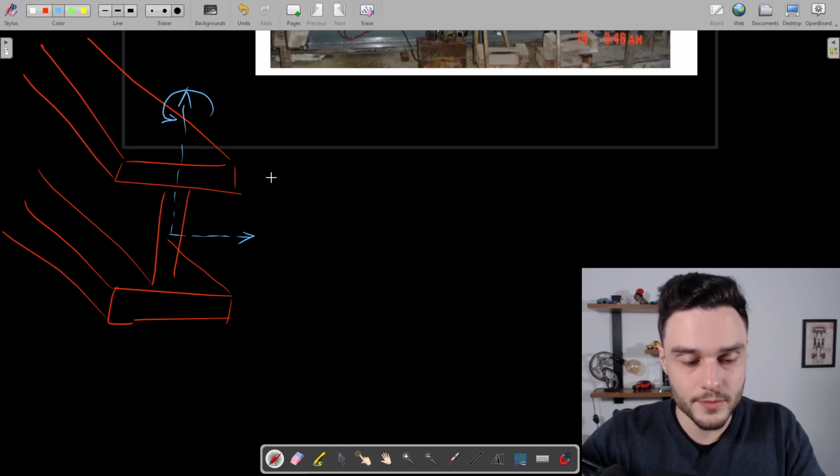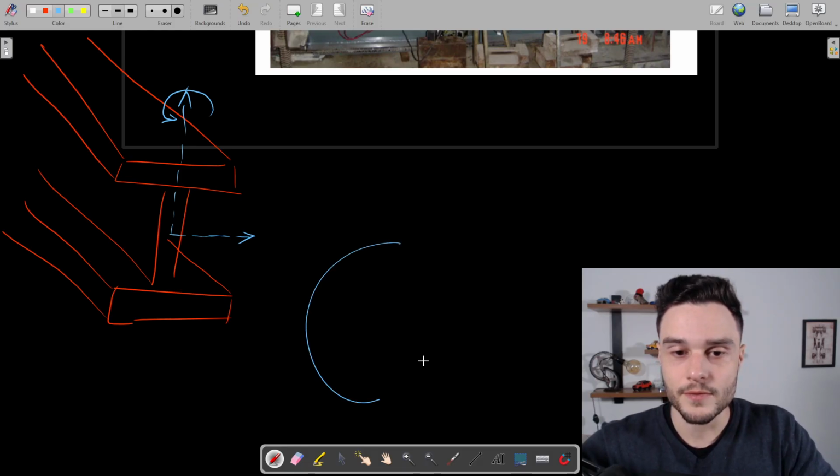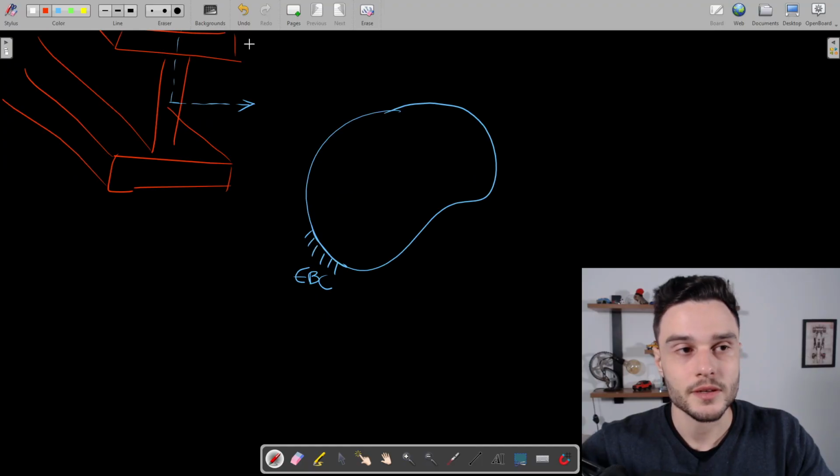It's important to remember some things that we have learned in the theory. So we have the domain, right? And then we have some prescribed displacements on some regions in the outer surface of this body. This is essential boundary condition. And then we can also have traction, which is the natural boundary condition.